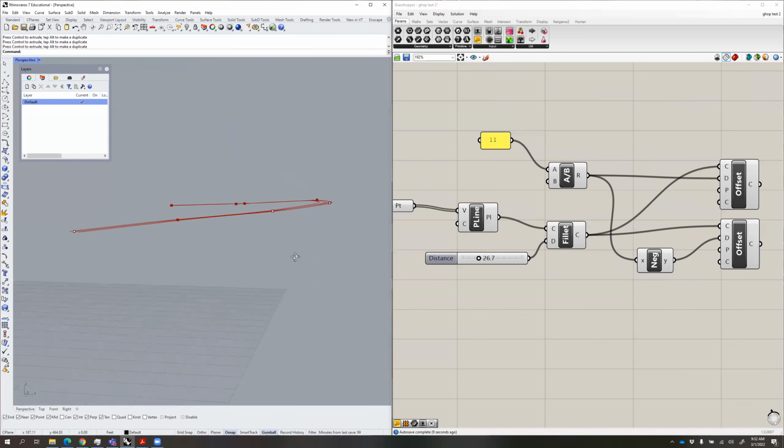And of course, this path is in 3D, so if you adjust the spot elevation of, say, one of the paths, let's say we move this down a bit, it still changes that. And so that's a nice way you can easily model a path.